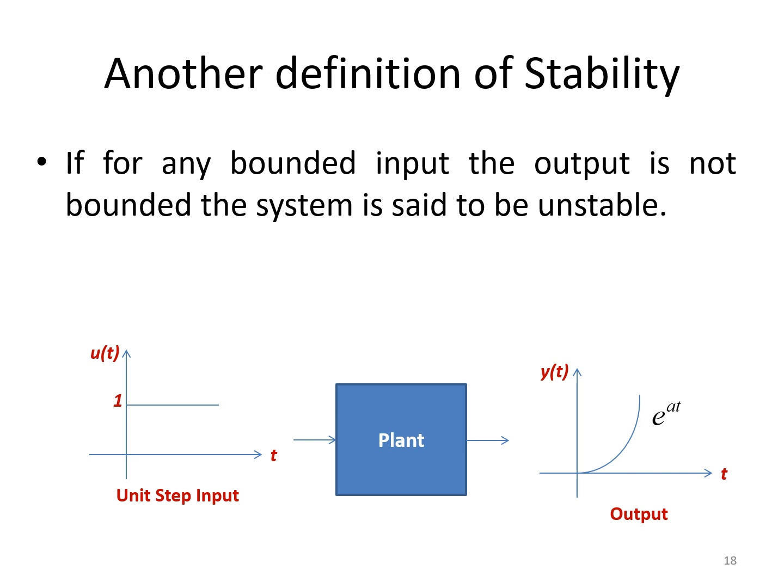Another definition of stability: if for a bounded input the system produces an unbounded output, then the system is said to be unstable. In the previous case, we got a peak overshoot, but the response comes to stability at some point, right? But in this particular example, even if I am giving a stable input, my output is exponential. I don't know when it is going to reach the stable value of 0. So this is an example of an unstable system.